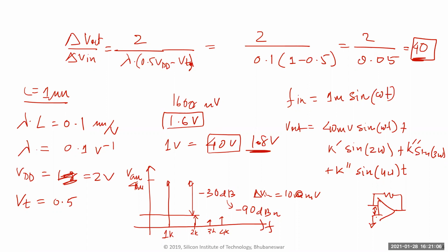So I thought this would be a good segue. You've used the inverter as a digital circuit, now you see how you can use it for analog, and now you know how you need to do biasing, right? You can't just take things and use them, you need to bias them, because in analog it's not just sizing them, the current also depends on how you bias them. In digital, you always just chose a size because your input was always a 0 or a VDD, and the size just took care of the transients, right? But here you're actually passing currents through them, so you need to bias them properly. I thought it covers a lot of things and gives you a nice transition into the analog world.